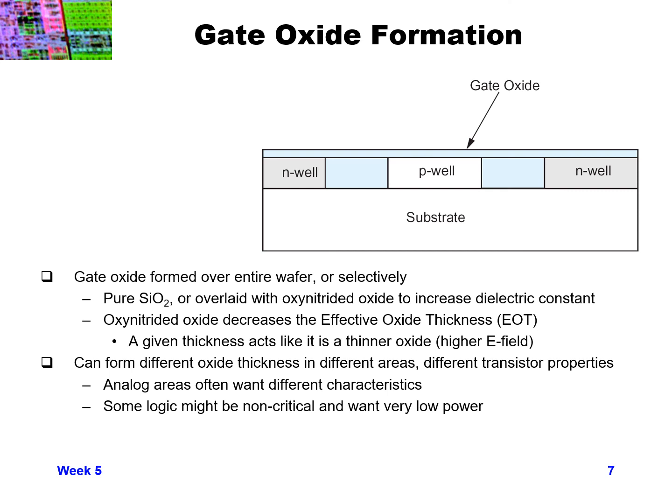So keep in mind, these seem like valuable things to have, which they are, but every time you add additional processing steps, so having two or three different oxide thicknesses across your wafer, it increases the number of processing steps. It's going to increase your costs. Time through the fab is going to be longer, and it might even decrease your yield because you're going through more processing steps. So everything you add that has a positive effect might also have some negative effects, and you have to weigh the positives and negatives against each other.